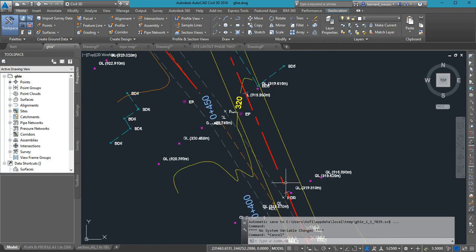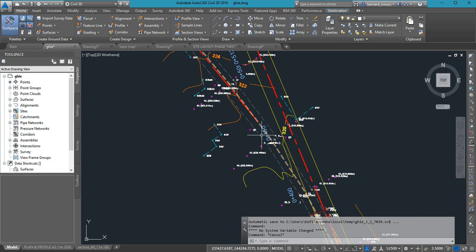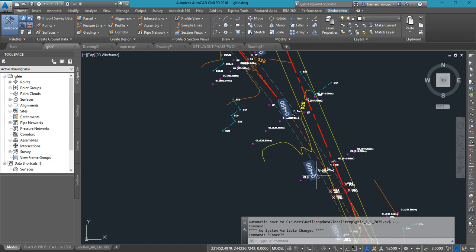Now I'm going to put in a curve. If you look at it, you can see that the deflection is very small. So it means that obviously the radius here will be very large. You understand? So you don't have to worry yourself with any mathematics or verification. You will see that here you need a simple curve. It's where you are in doubt that you may want to first put in a simple curve, then check. If the radius is below 330, then you change and rather put in one with spirals.